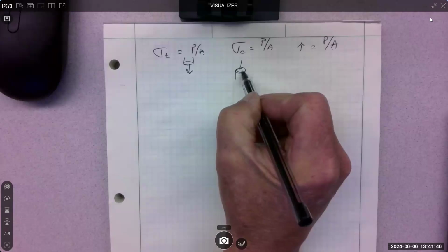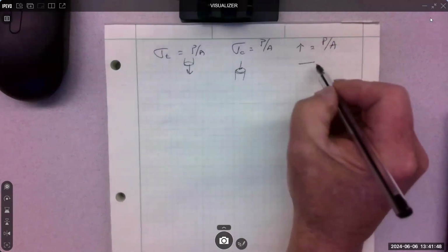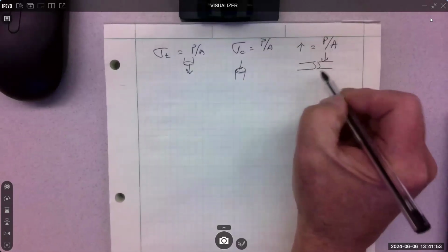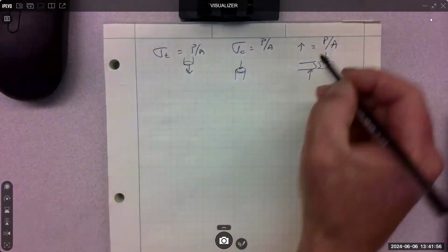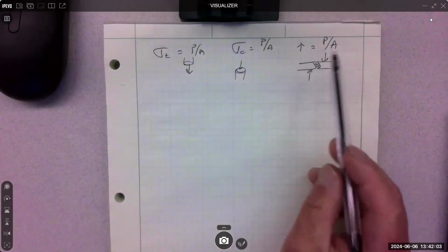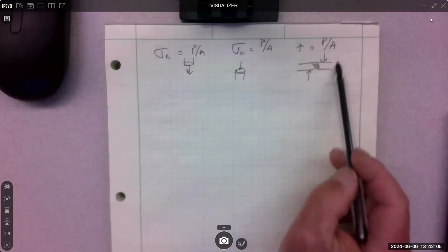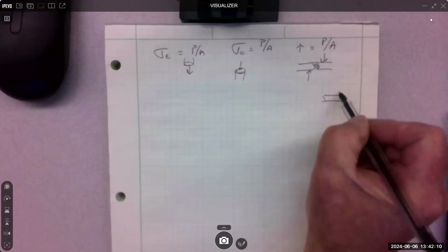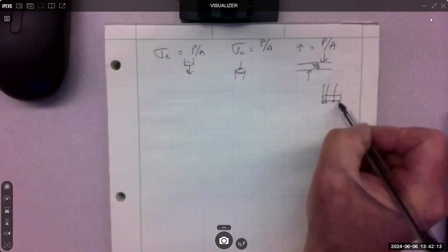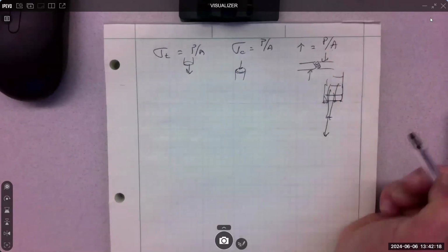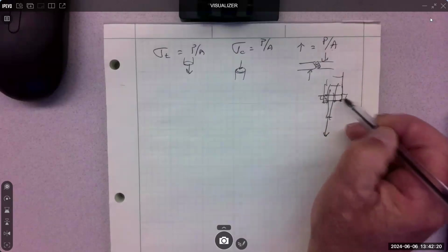Load is perpendicular to the area, but shear, like I'm gonna shear this thing off, the load is parallel to this area. Right? And what was the tricky part about shear? Anyone remember? Like if you had a pin and it's got a connector here, and then this connector here is pulling this way. That's a bad drawing. Like a connecting rod to a piston.